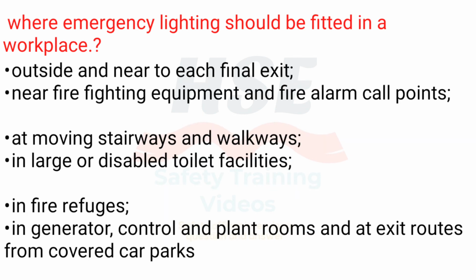Outside and near to each final exit. Near firefighting equipment and fire alarm call points. At moving stairways and walkways. In large or disabled toilet facilities. In fire refuges. In generator, control and plant rooms and at exit routes from covered car parks.